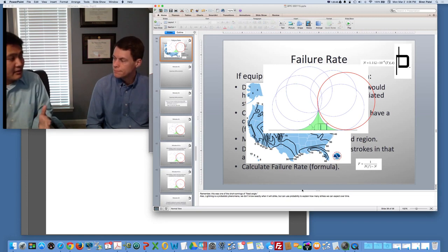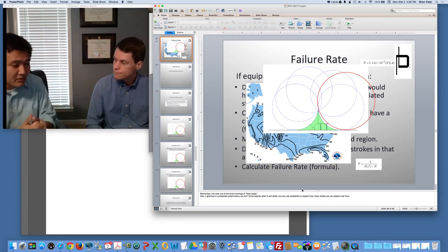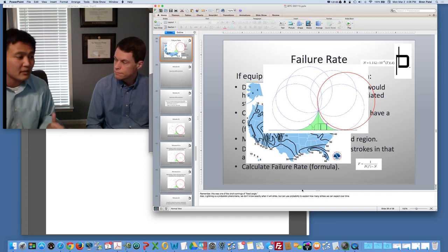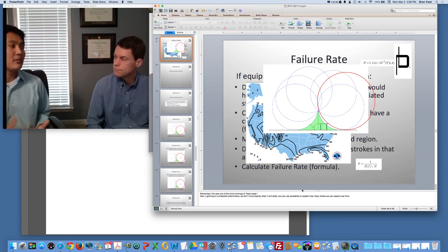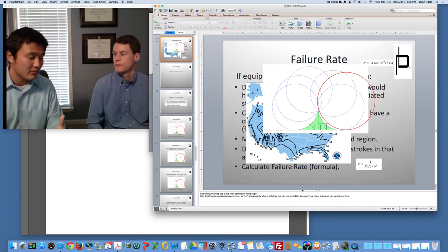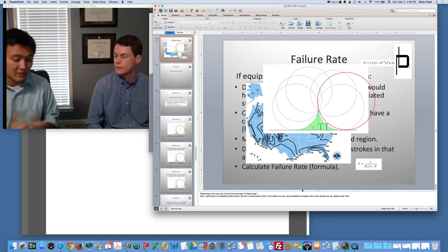Whereas if you're in an area that uses concrete, maybe an area that has tornadoes, tornadoes will blow everything down. But higher wind speeds because of hurricanes, or soil reasons, for whatever reason, if they're using concrete, then they may say, well, we're willing to accept a lower value of failure rate because it costs a lot of money for us to put in a new mast. Yeah, so that's some considerations.